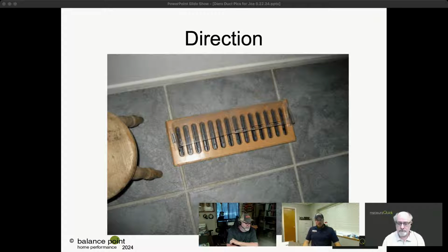But when we talk about Manual T, it's really just how that air distributes within that room. If we're not distributing the air through the room, you sit right next to that register, it feels great. You go across that living room to the other couch, it's not going to work. It's not going to feel comfortable.